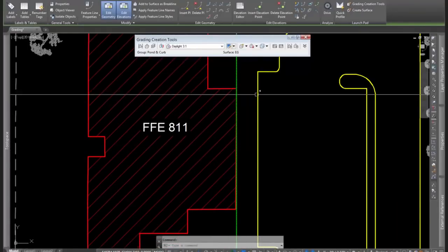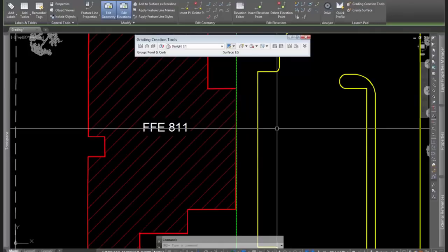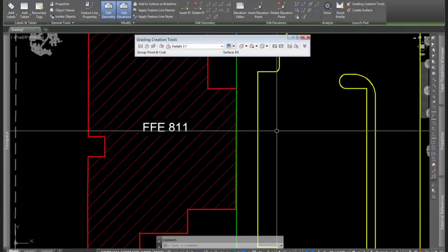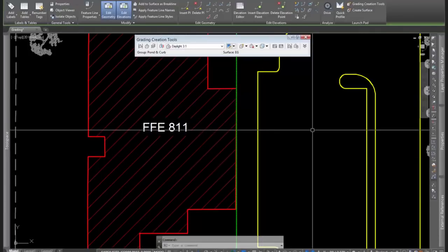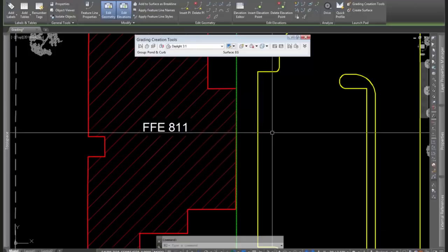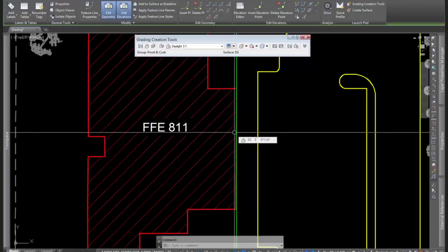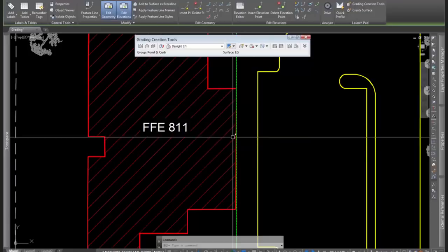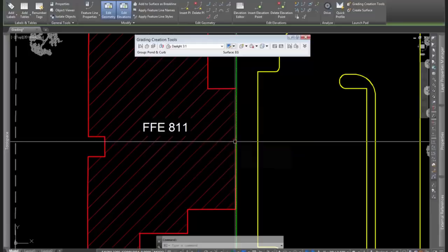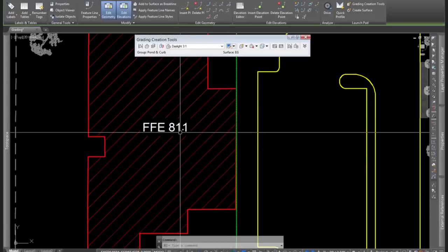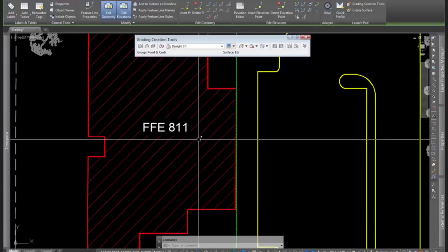what this surface is going to represent is the pavement grades. So the elevations out here of the pavement. If I were to take that, say we're grading 2% to the east, if I were to take that grade or that plane and extend it up to the building, I would want the start of that grade to be roughly a foot below, or excuse me, a half a foot below finished floor, because I have a curb drop.